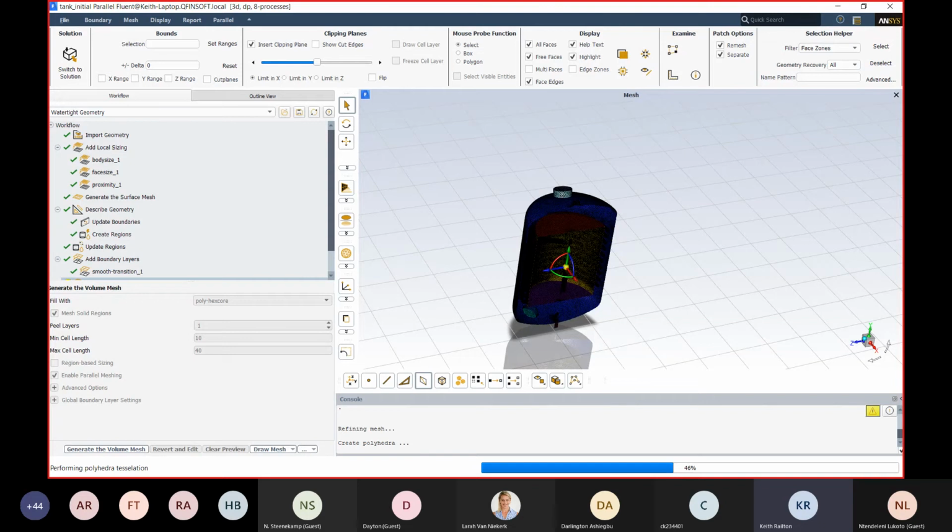If we want to, I can delve into it in more detail later on. I can show it in equations, what is required, but ideally you want a y plus of less than 5 or less than 1 for good pressure drop and heat transfer calculations.